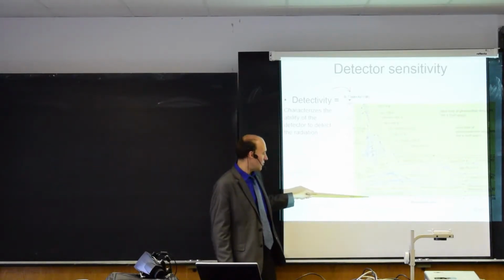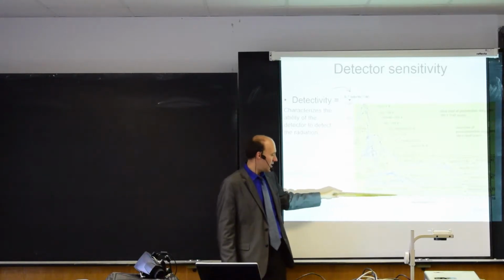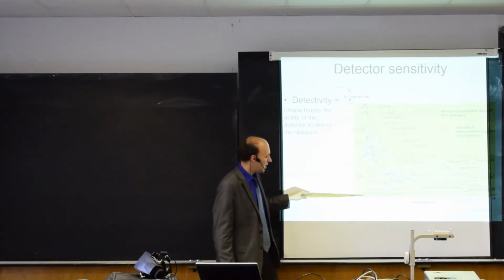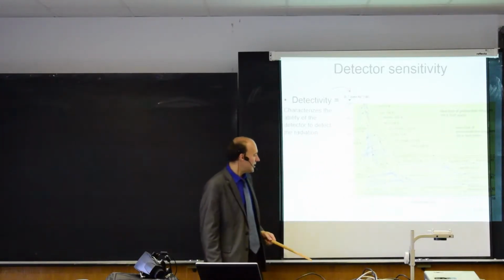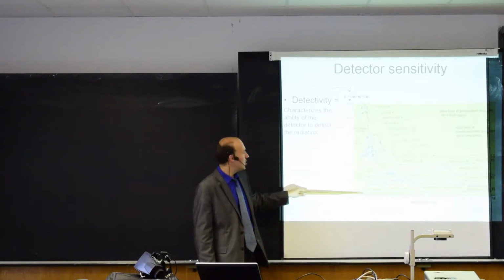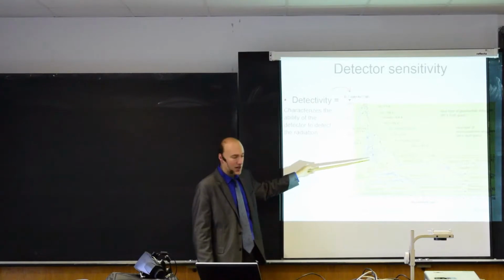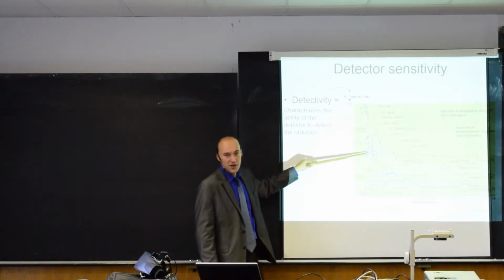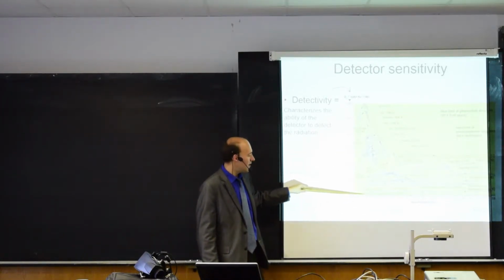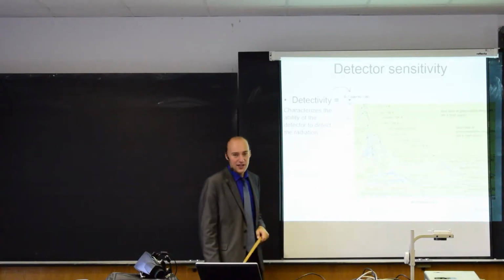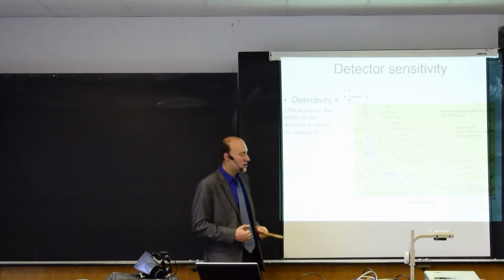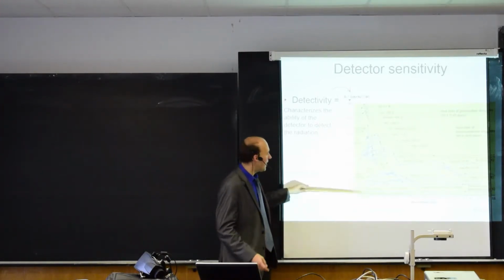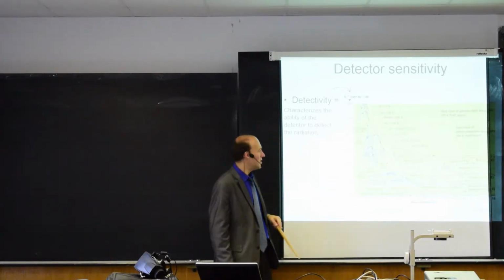Here we see one interesting thing, thermistor and bolometer. So you see it has quite a nice characteristic from 1 to 17 micrometers. But if you compare that to the other materials, you see that the detectivity is much smaller, a few orders of magnitude smaller. So a thermistor is a really nice sensor for infrared radiation, but it has a really small sensitivity. If I want something more sensitive, I definitely need to take those materials.